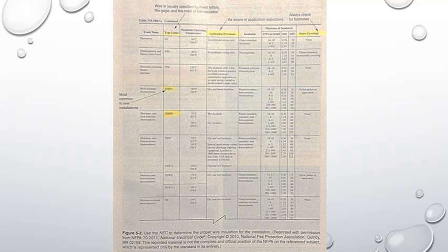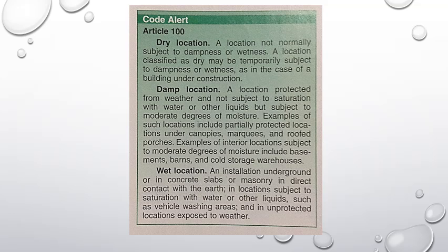Insulation. Conductors that normally carry current must have a non-conductive covering called insulation. Acceptable types of insulation are listed in Table 310.104(A) of the NEC, which was the figure just prior to this one.